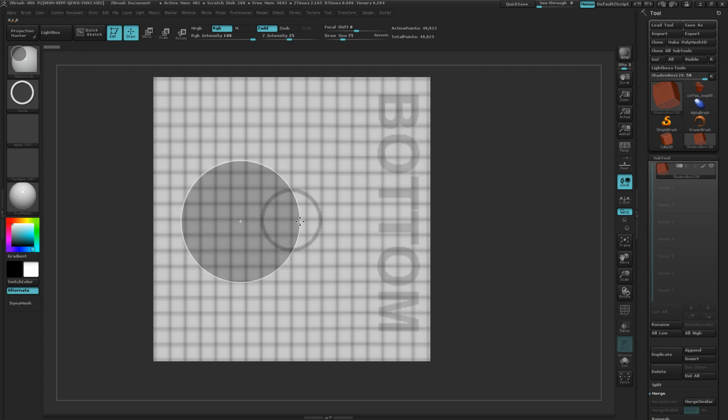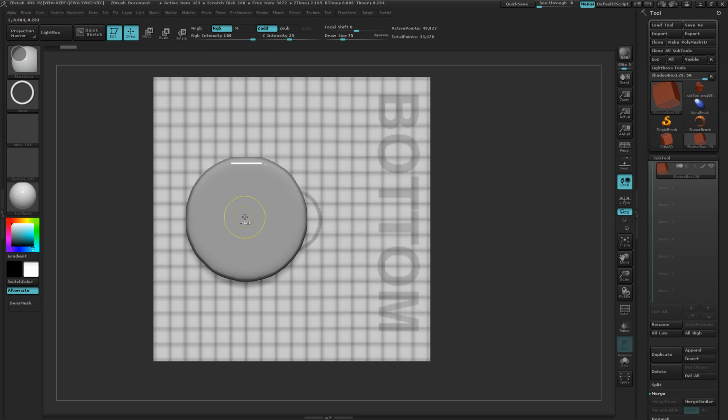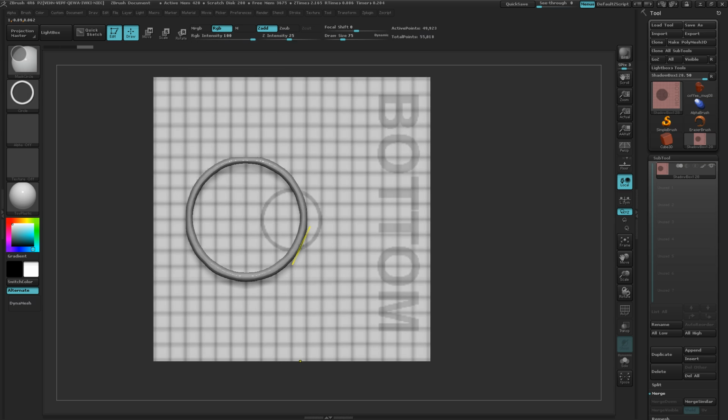And I'm going to move it over a little bit because I want to have some room for the handle, but I do want to keep it centered there. So let's maybe center it on that line right there, and let go, and you see that gives me my cylinder. And then I can hold down Control again, draw another one out, get it roughly centered. Let's see if we can get it a little more precise. And then drop it in some, hold down the Alt key so it's a negative, do that, and that gives me kind of the barrel of the mug.